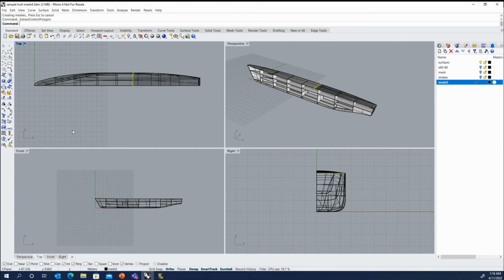So you can click on a trimming edge in the surface that was used to create that hole, and it'll close it up. When I need to do that, what I'll typically do is make a copy of the surface and retain the original that has the openings in it, because you'll probably want those openings later for reference when you go to create the openings in the mesh. But for purposes of generating the mesh, sometimes I want to create the mesh without all of those openings in it.